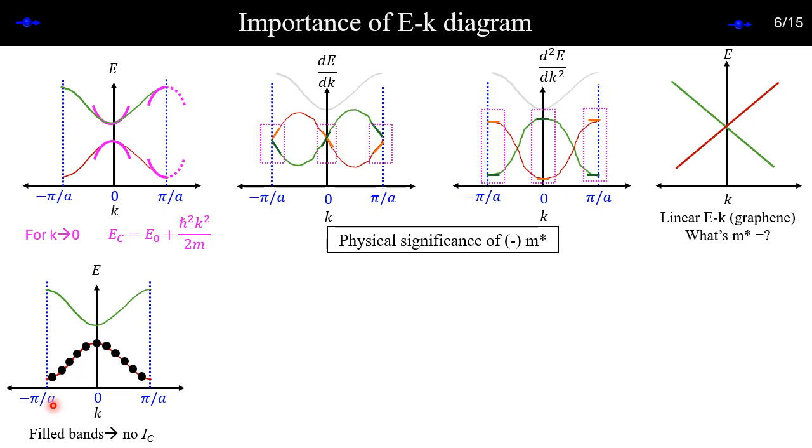So what does it physically mean? It physically means that you have a silicon crystal, with silicon atoms all over. If it is a perfect crystal, we have covalent bonds everywhere, no bond is broken. All electrons are participating in the covalent bonds. If they are bonded, you can't move them, so net current is 0. Bonded meaning, that's why it is called the valence band. Is it okay?